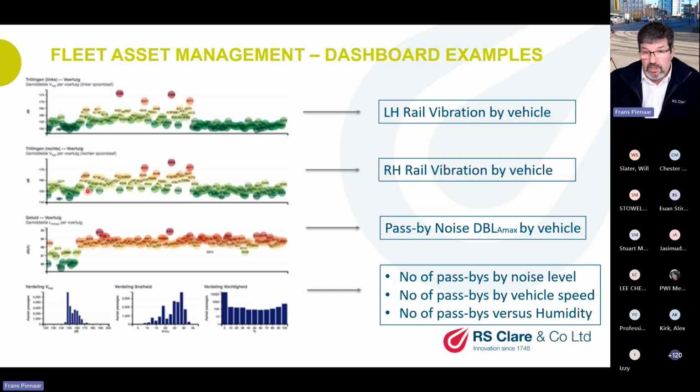The ones that are green show that all the noise measurements are the same as against the benchmark that you did previously. The bottom one is noise, and this most probably shows that you have maybe 2 or 3 different train variations running on the same line, passing this monitoring equipment. So you have a train that has no noise, and then one that has maybe some noise, and then a train set that has quite a bit of noise, or a type of train that has a lot of noise. And that can be related to the wheel profiles, anything that changes on the trains.